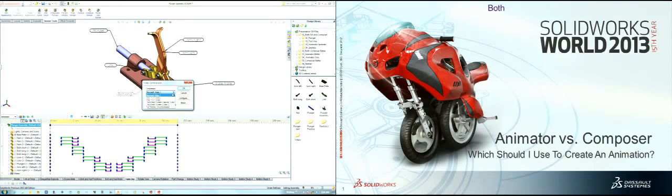One little tidbit is people think that codecs are in SolidWorks. No, the codecs are stored in Windows. What you're seeing for a list of codecs is what's loaded on this computer, just like you saw it over on Composer. She had a different list of codecs because that's what's loaded on her computer. One of those other fun facts is we see posts in the forum all the time that says, hey, I loaded this codec and it's not in the list.